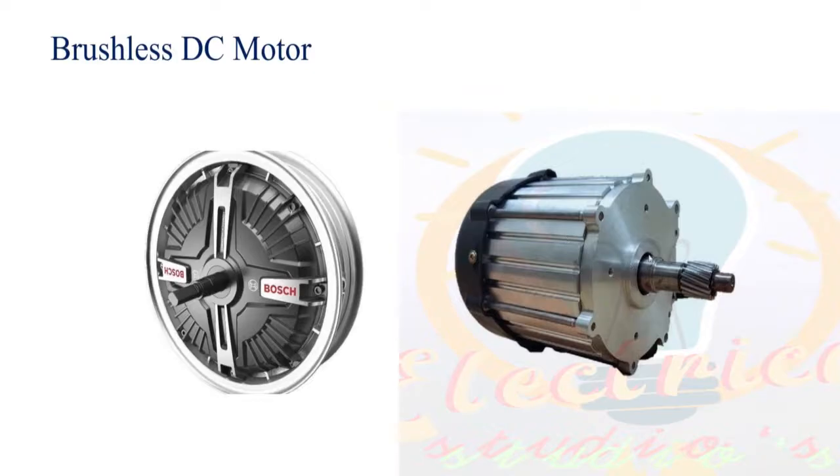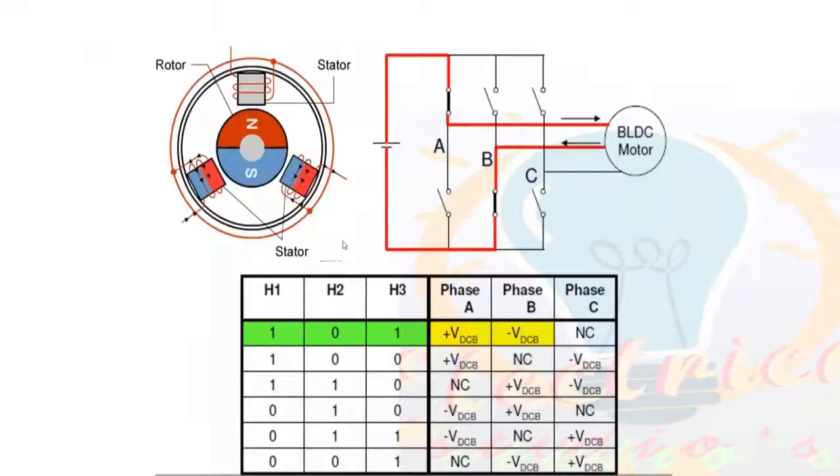a mid-drive motor. When the power capacity is more, when your motor power is more, then temperature generation will be more. So when the temperature is more, there are more problems that could come inside the motor. Losses will be more. So that is why whenever the power capacity is low, they select a hub motor. Whenever higher powers are there, then they go for the mid-drive motor, as I mentioned.